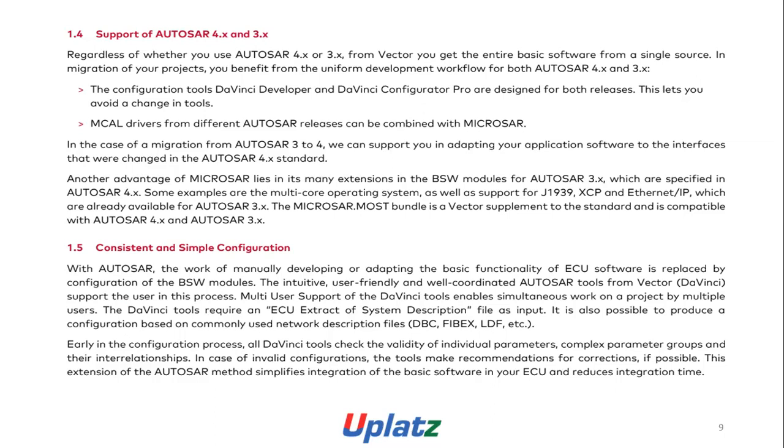Consistent and simple configuration with AUTOSAR. The work of manually developing or adapting the basic functionality of the software is replaced by configuration of the BSW modules. The intuitive, user-friendly, and well-coordinated AUTOSAR tools from Vector, DaVinci, support the users in this process. Multi-user support of the DaVinci tools enables simultaneous work on a project by multiple users. The DaVinci tools require an ECU extract of system description file as input. It is also possible to produce a configuration based on commonly used network description files: DBC, FIBEX, LDF, etc.